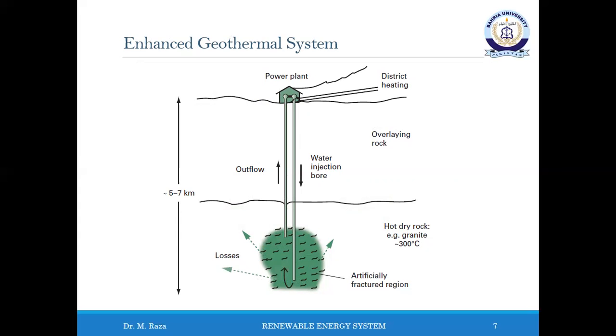The depth of boreholes can go up to 7 km. The pressurized cold water then reaches the end of boreholes and becomes steam due to the hot rock. This steam returns through the shallow return pipe. Using such enhanced geothermal complex arrays of injection and return boreholes might, in principle, enable gigawatt supplies of heat to